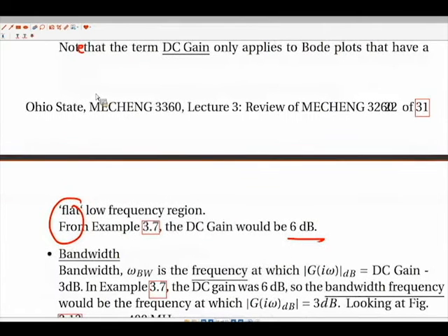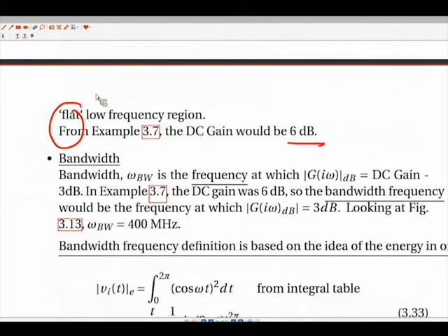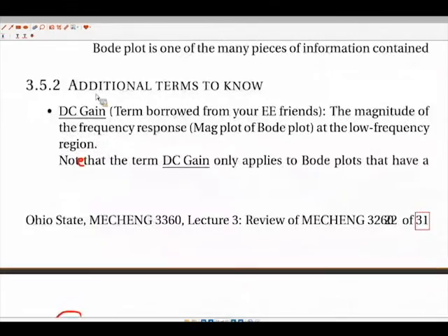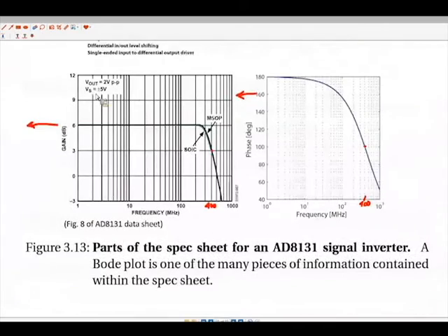Okay. So bandwidth is always a frequency. If you ever ask what the bandwidth of a system is, and you provide an answer like 6 decibels, that's wrong. In this case, it's 400 megahertz, but the bandwidth is essentially the operable range of the system. If we try to put in a signal of say 1 gigahertz, or 1,000 megahertz, our output magnitude is going to be very, very small, in the range of -6, -8 decibels or something like that.